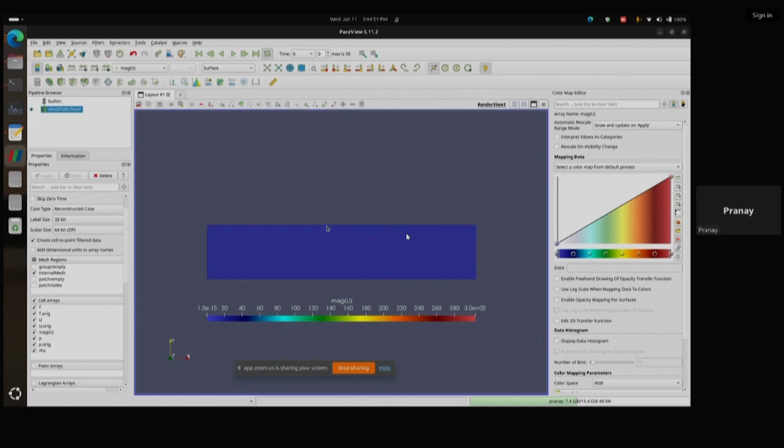Yeah. So at time zero, the entire field value is zero. Okay. At first time step, we can see the shock. The shock is forming, and this region which was having a velocity of zero suddenly at 0.0005 has a velocity of around 240 to 300. In the small region around 1 meter, the velocity is changing from 20 to 300 meters per second. This once again happens because there is shock formation and it will propagate ahead.